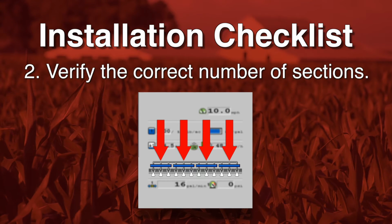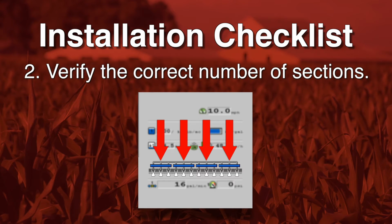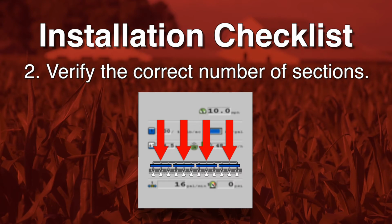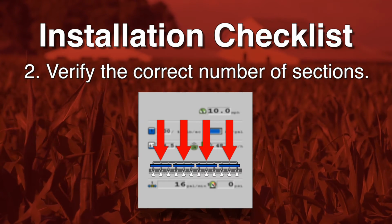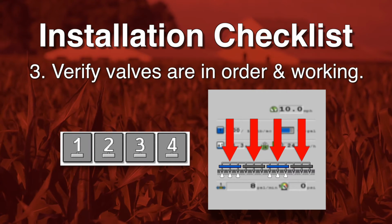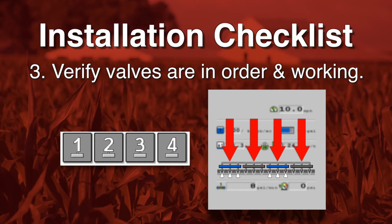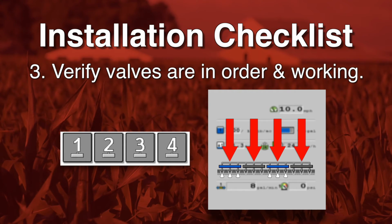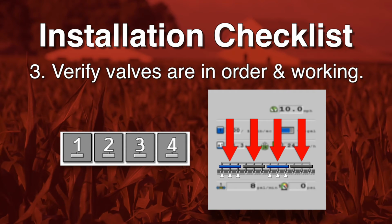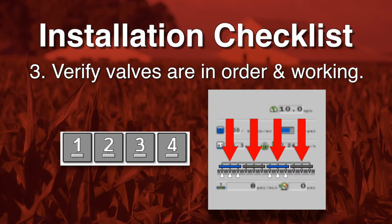Secondly, verify that you have the correct number of sections by counting the blue bars on the universal terminal. If you are running 4 sections, you should see 4 blue sections on the display. Thirdly, double check that your valves are in the correct order and are functioning correctly. Use the soft key buttons on the universal terminal to verify this. Visually and/or audibly confirm that the valves open and close with the use of the soft keys.